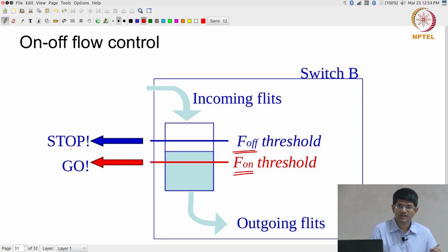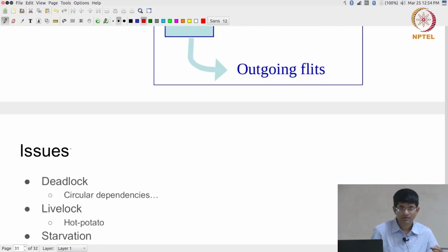The most important thing to keep in mind is, although I said that you can benefit from a lot of the theory of networks, trying to implement those complicated network protocols on a chip is almost certainly a bad idea, because in software you can allocate buffers, you can store data, you can retransmit, you just have some if statements over there. But in hardware all that translates into more and more gates, more area, more capacitance, more power consumed, more cost, much more than what it would be in the software. So that's why all of these different techniques are going more towards a hardware friendly way of implementing things.